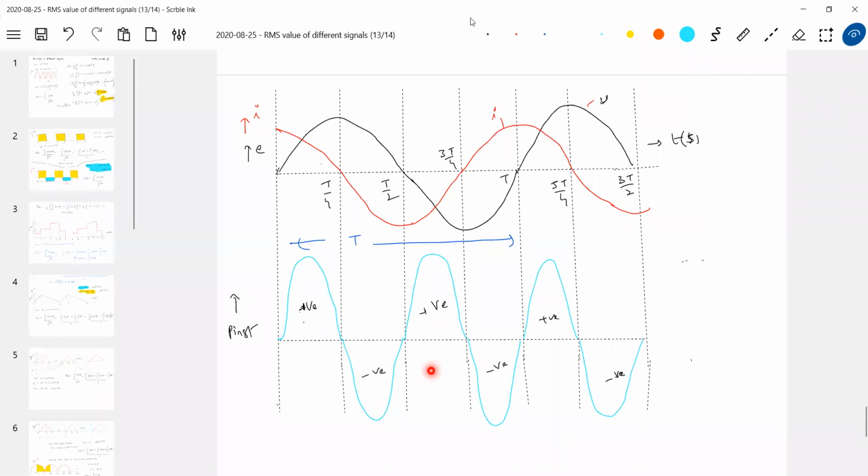It's an energy storing element. There's exchange of energy between the source and the capacitor, and that exchange occurs twice: first it draws energy, and it returns back; again it draws, again it returns back. When the signal completes one cycle, what happens to the power cycle? It completes 2 cycles.